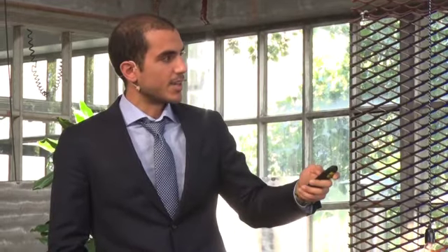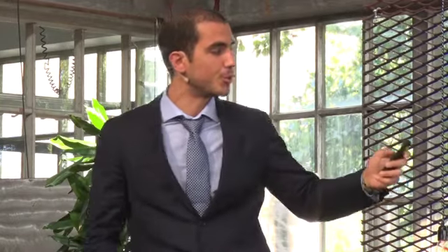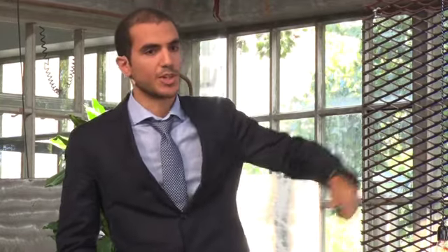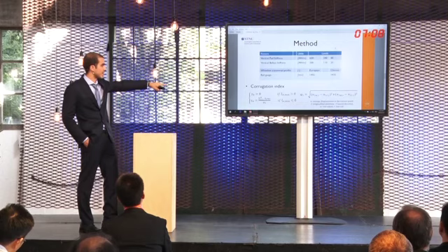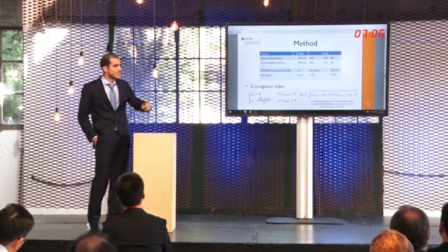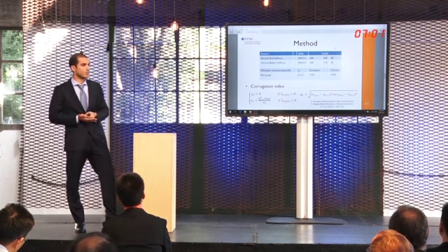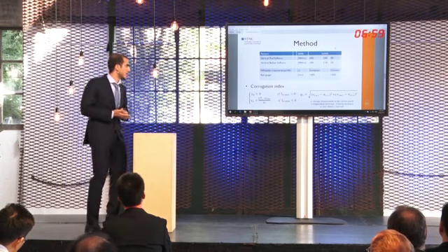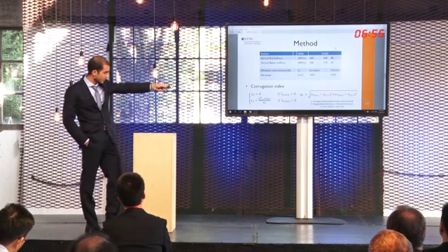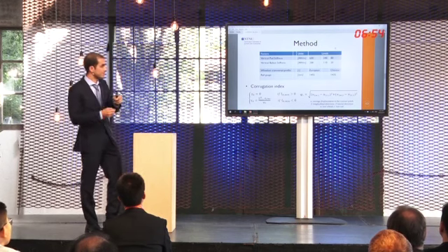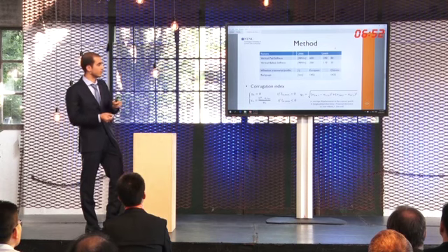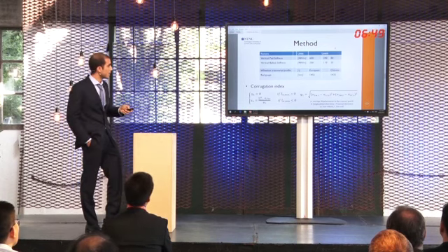Finally, we have defined a corrugation index that takes into account both the instability of the system in particular situations, through the negative effective damping ratios detected, and the ability of this unstable vibration to generate wear near the contact patch, through a slip ratio that considers the difference of the displacements between the wheel and the rail near the contact patch.